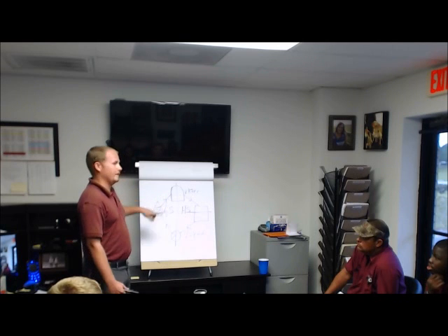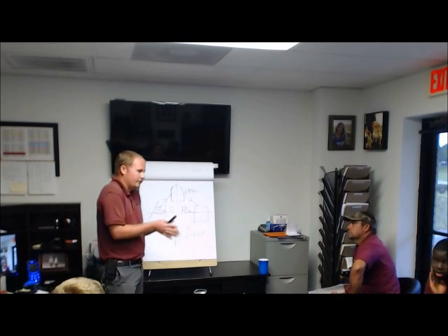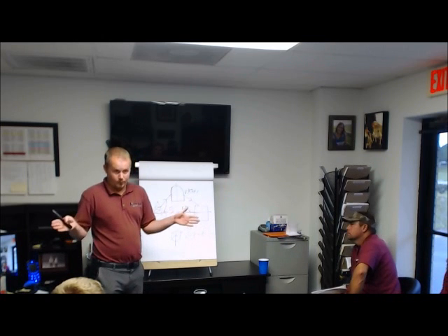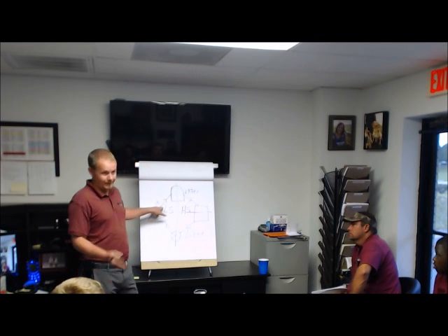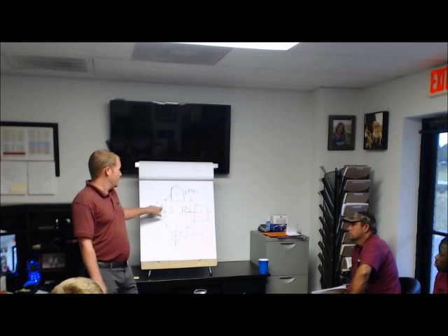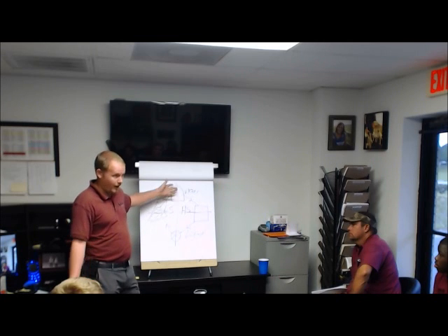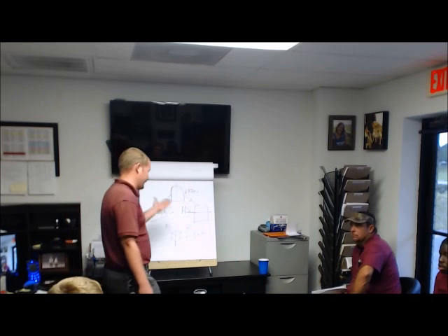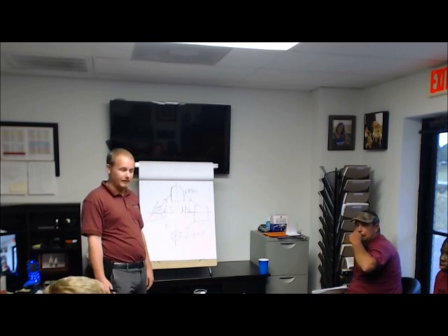Maybe. Right. That's the balance that you're making there, because you do want to use up as much of the coil as you can, as is reasonable to use up. But you don't want boiling liquid, change of state, refrigerant traveling down the suction line towards the compressor. Why? You slug the compressor, which means what? Yeah, you'll get liquid back in the compressor, which dilutes the oil and causes oil migration and all kinds of different nasty stuff.